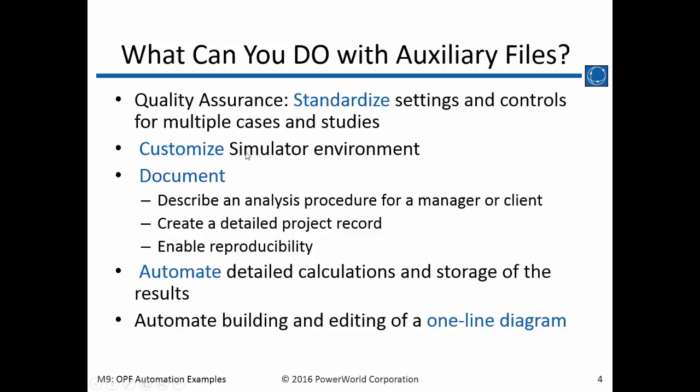So you can customize the environment, things like area zone filters, things like display grids, what fields you like to see with different displays in the Model Explorer. You put that in an auxiliary file, and then you don't have to make those changes manually each time.